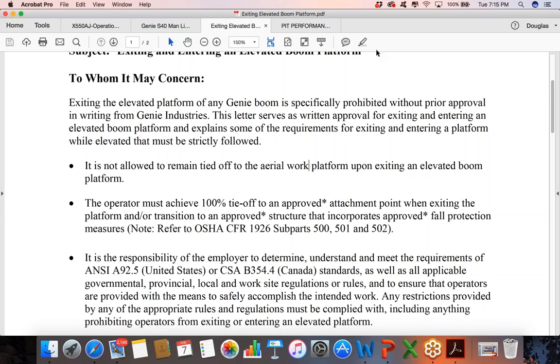In addition to that, we want to make sure that the most common circumstances, like we said, are falling from a roof or falling from a leading edge. I'm moving on, folks. I'm on module 6, page 2 now. Ladders and scaffold hazards, so we want to be cautious of those as well. They could cause significant fall hazards, and we also want to make sure that we're working on stable work surfaces. Some risk can be avoided by tying off ladders or properly installing fall protection systems.